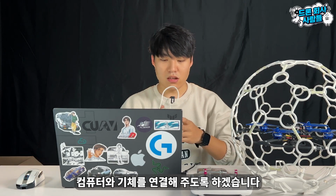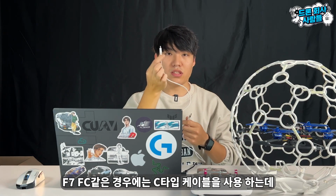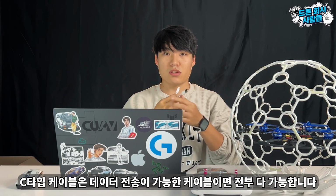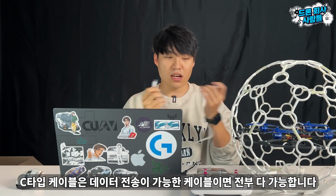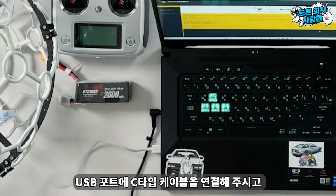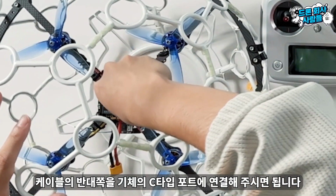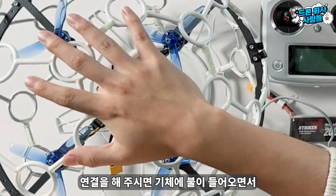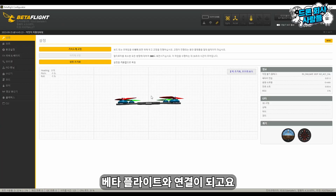Now let's connect the computer and the aircraft. In the case of the F7FC, it uses a C-type cable, and any C-type cable that can transfer data will work. Connect the C-type cable to the USB port and then connect it to the C-type port on the aircraft. When you connect it, the lights on the device will turn on and it will connect with Betaflight.